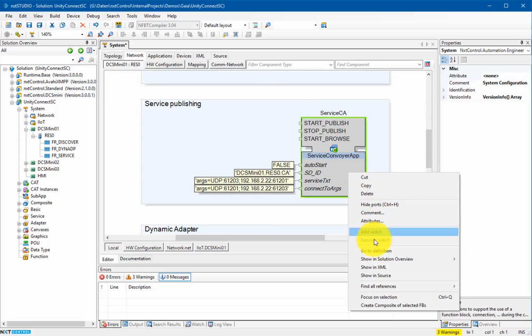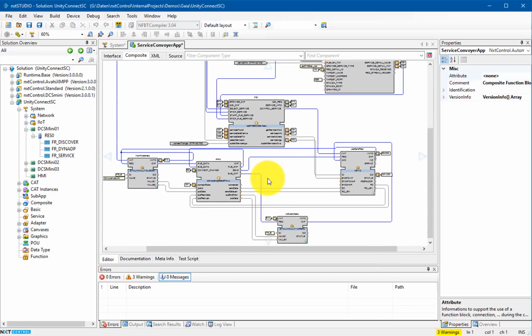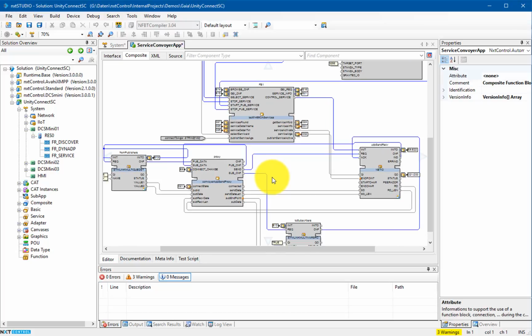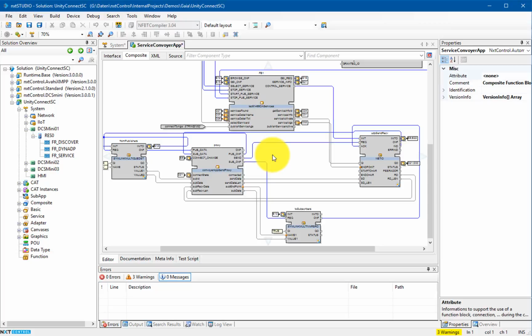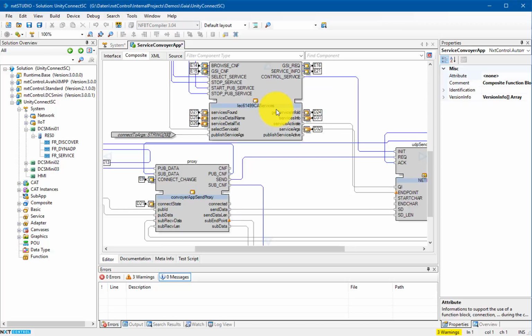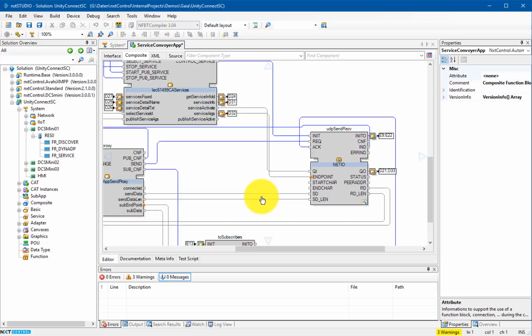An application service function block consists of the function block network of the HMI interface, the service discovery interface, the service connection interface and the service configuration itself. All of these function blocks are used on the one side for discovering the service and on the other side to establish the connection to the raw UDP socket connection if the service is needed from one of the applications in the automation environment. With the services discovered, we can now have a look into the application level of our demonstrator.